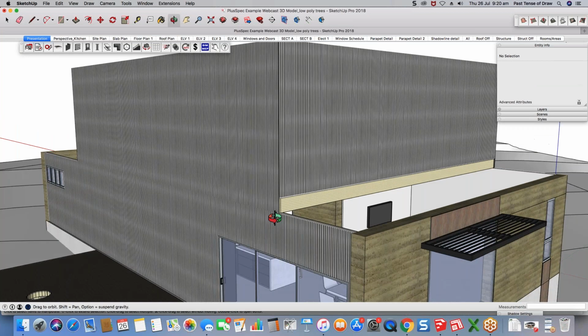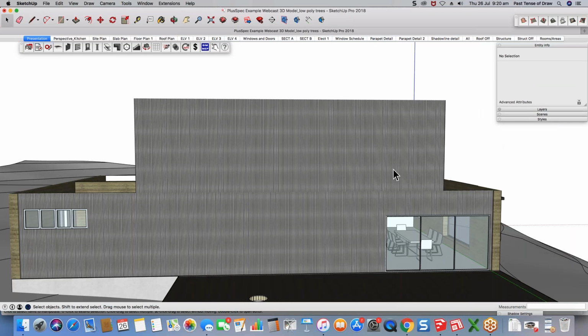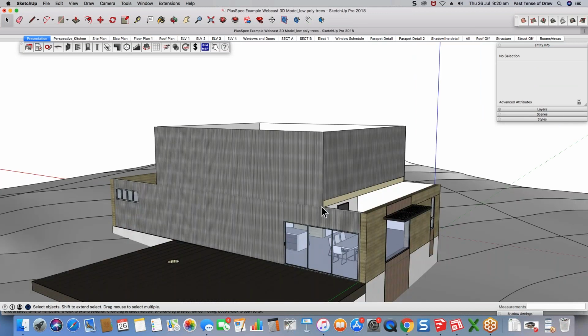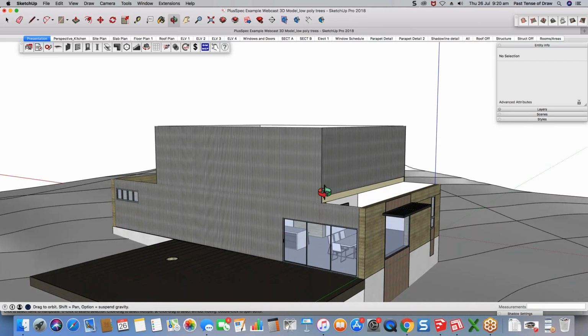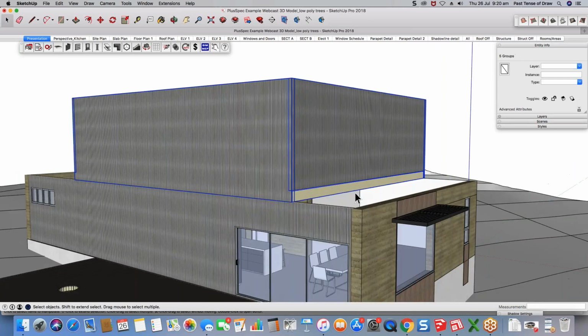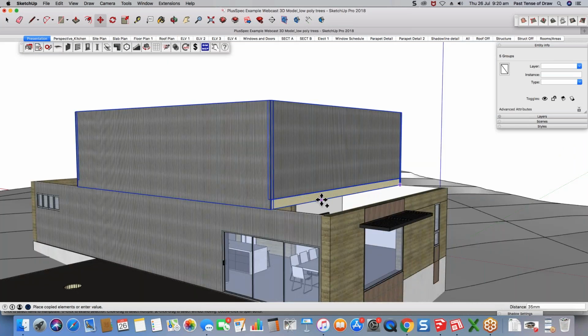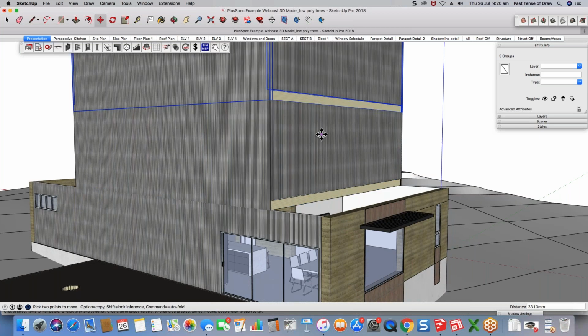And now you can see that it's reading as 1. You can see the cladding, you might need to tidy it up if the material is not aligning correctly, like 100%. You can actually clean that up, etc. So you can go through and really start to mass out your floors. And again, I could now just simply grab everything that I want here. If I've got an additional level, I can simply continue to grab the elements or the objects that I want and place them so I can go up to a third story. And then obviously if I really wanted to, I could be sculpting my walls, pushing and pulling them and doing whatever I wanted.